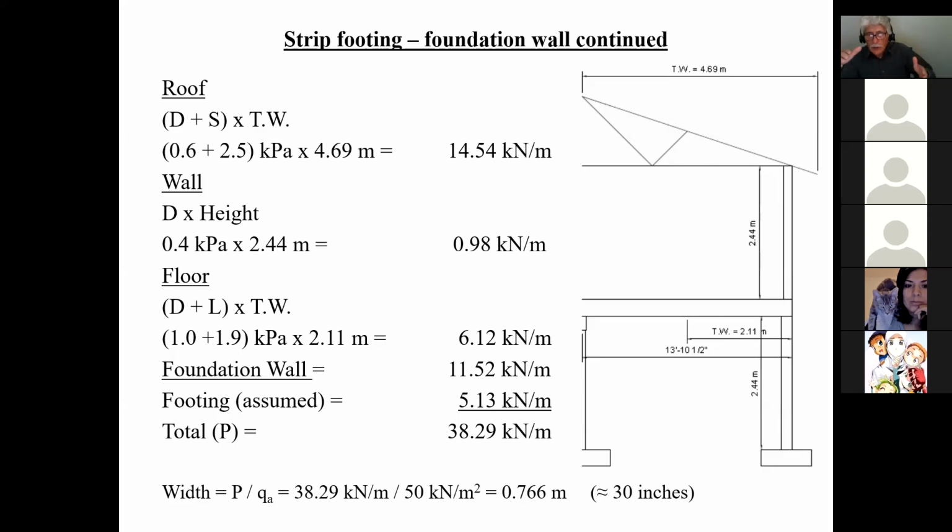Go 30 and then use multiples of 6: 30, 36, 42, 48, and so on. So in other words, 2.5 feet, 3 feet, 3.5 feet, 4 feet, and don't go into 2 feet 10, use multiples. And guys, don't worry, okay? Make your footings big enough so that you don't have a problem with settlement, because that's the worst thing that can happen. Once it starts to settle, it's all kinds of money. So when they're building this thing, to pour that extra concrete, it's peanuts.